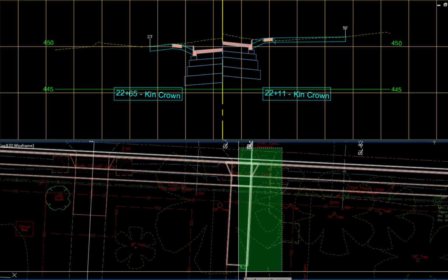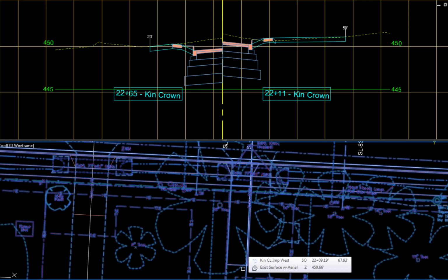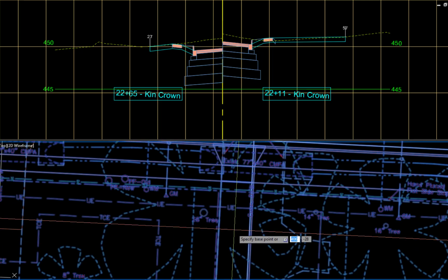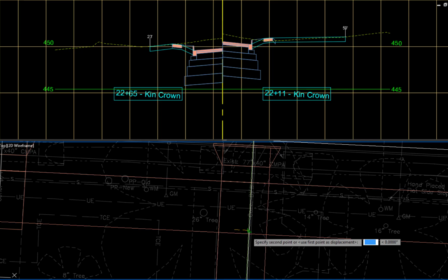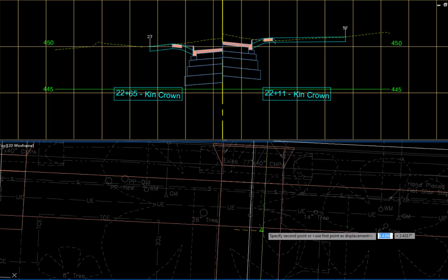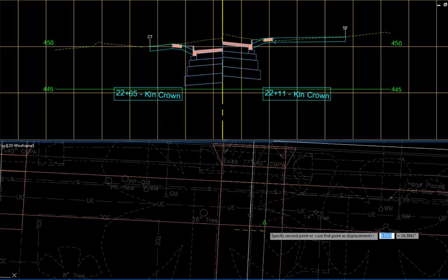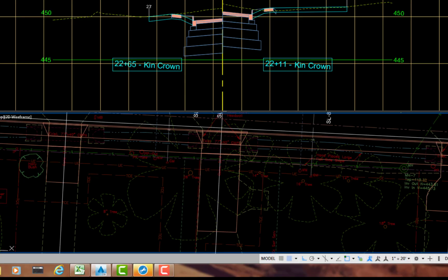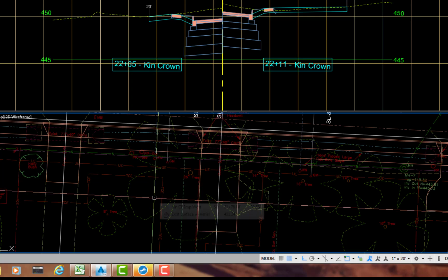Select the right portion of the driveway. Enter. Pick a point in the vicinity of the driveway. Move at right angles towards the direction of the stretch until the edge of the template coincides with the edge of the original driveway. And pick. Modify the driveway as needed to conform to the original layout configuration.